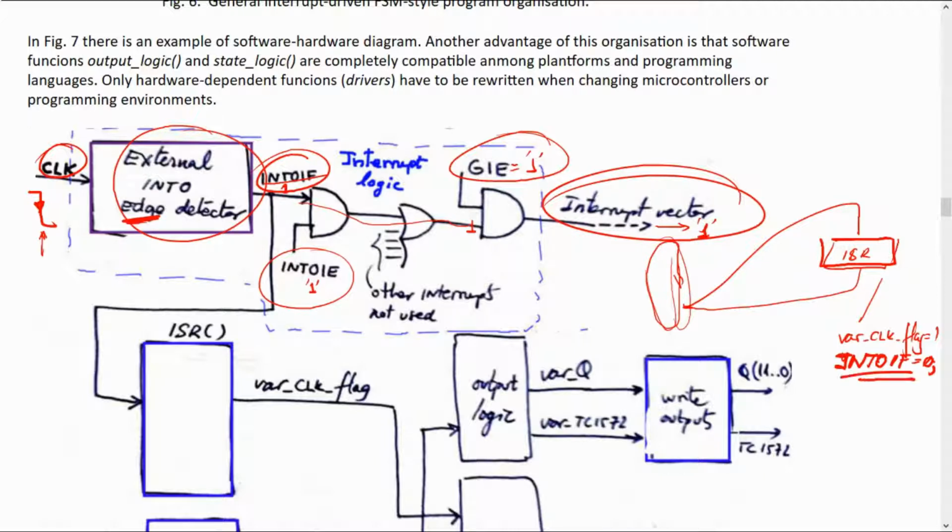Okay, so that later on another flag can be detected in the same way. So when you do that, this int external flag comes back to 0, and so you have no other access to the interrupt service routine until this event happens again later on in time. So that is remarkable, and that is the great thing in this kind of structure and architecture of a microcontroller, because naturally when things start being complicated or with a lot more features, you have many sources of interrupt. Okay, that is the thing.